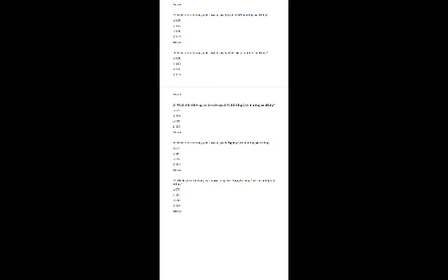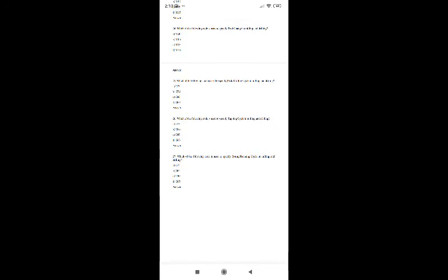Which of the following code is used to specify peck drilling cycle in milling and drilling? Option A G73, option B G76, option C G87, option D G83. So here the correct option is option D G83. G83 code is used to specify peck drilling cycle in milling and drilling. Now let us see the next question.